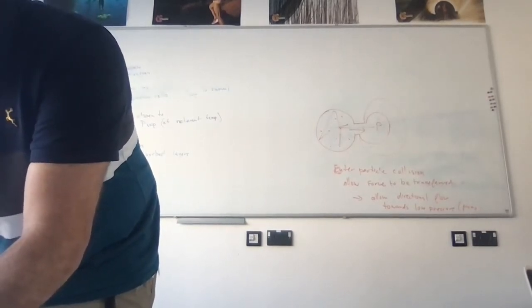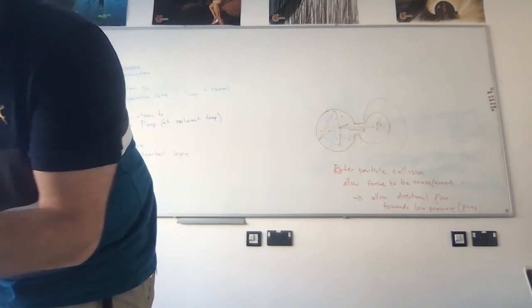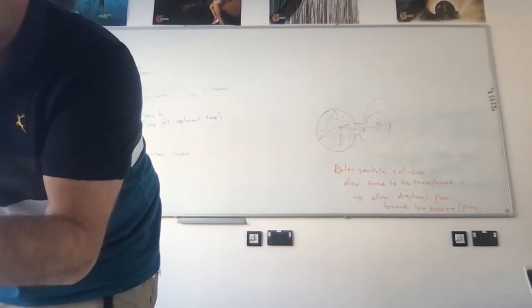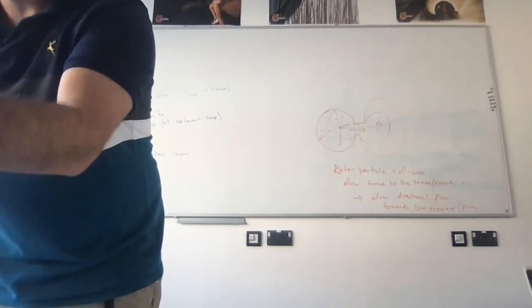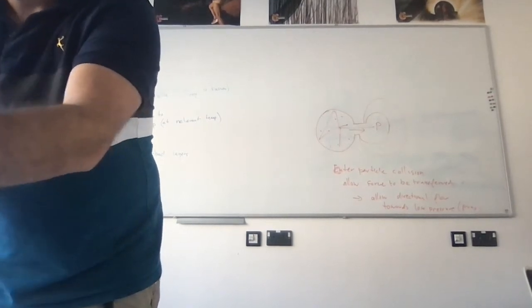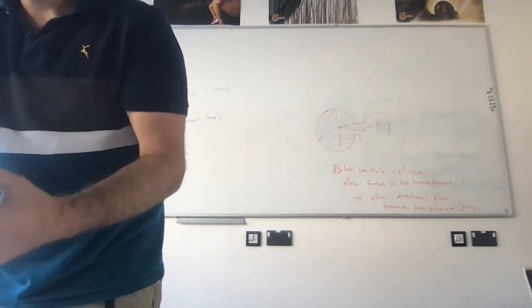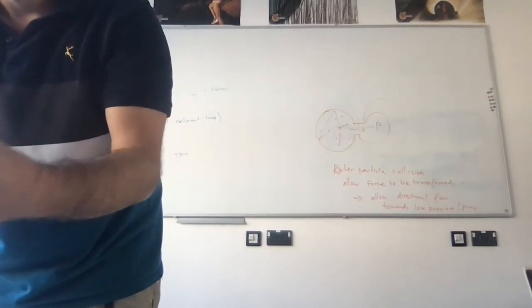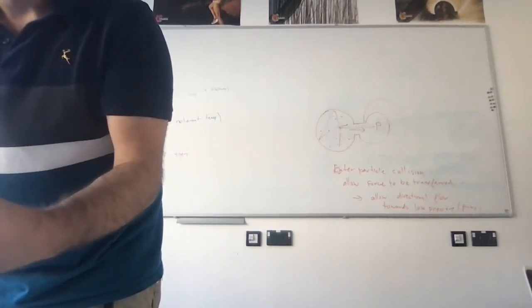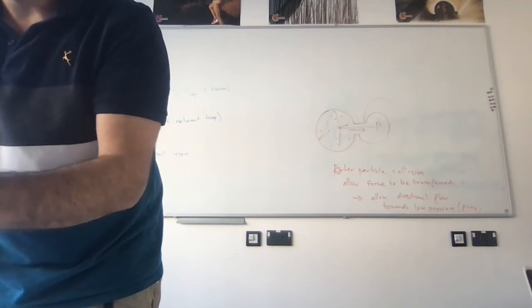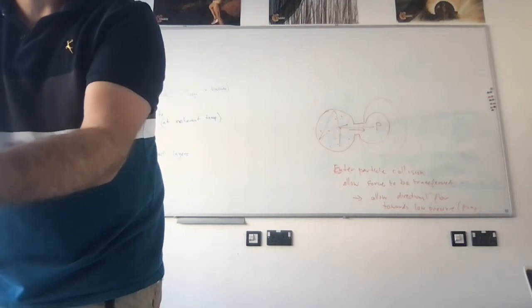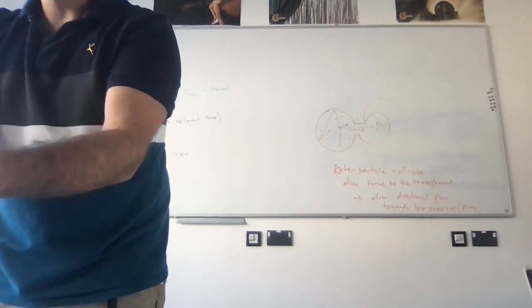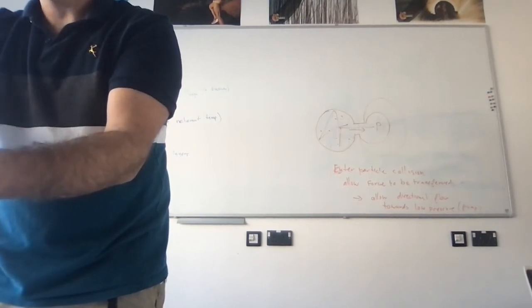This guy is a piston pump, where essentially what you have here is a thing which goes up and down. There are two ways the gas can come out of this, either to the right chamber or to the left chamber. And you have these one directional valves. When gas is going in one way, it pushes this piece of rubber out of the way, but it won't go the other way because it's sealing.